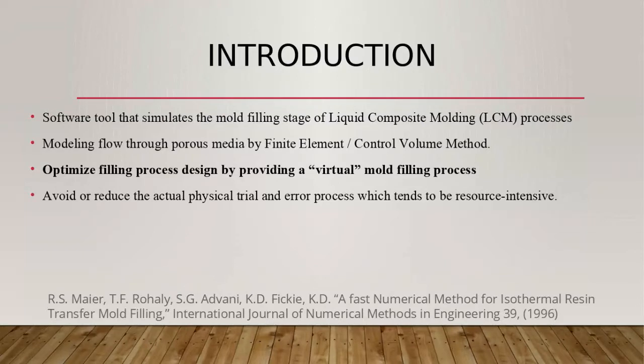And we are going to be defining the modeling through the finite element control volume approach, which means that when you have, let's say, for example, a 1D model, where you have a fiber fabric preform, and you are going to discretize it into N number of nodes in the X and Y direction, and you are going to propagate the boundary conditions from one element to another moving forward.